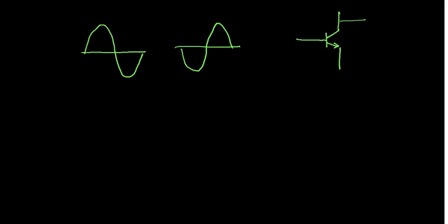There, if I am taking the output from here, as the input voltage increases, what will happen? This will turn on this. More IB, more IC. But if there is more IC, there is a resistor there. This will get connected, and the output will be shorted, right? I mean, the path will be at 0.